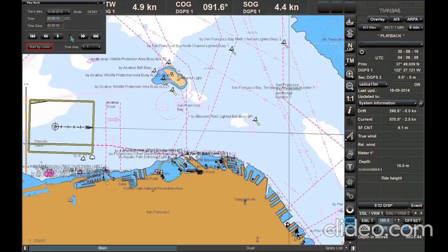Click the Start by Cursor button to place the Own Ship symbol on the Own Ship's track at the point where the situation playback should be started. Set the ship symbol in the required track point using the mouse and click. The playback of motion will start from the point where the ship symbol was set.